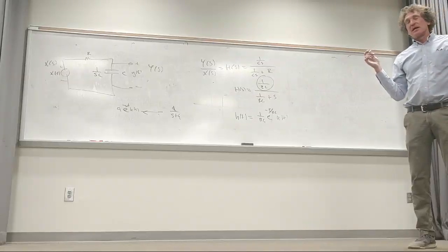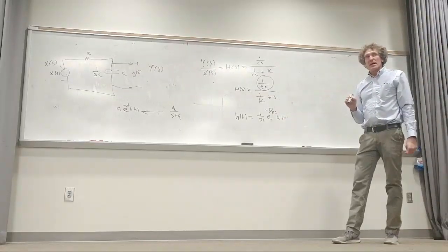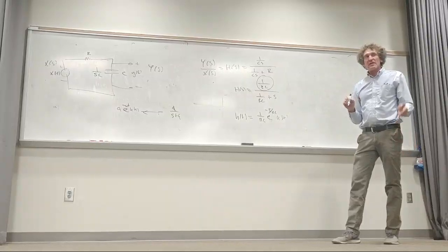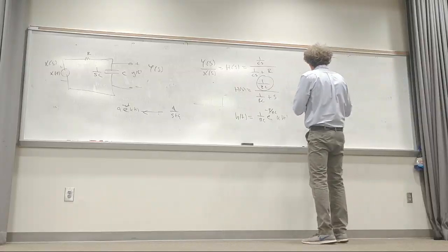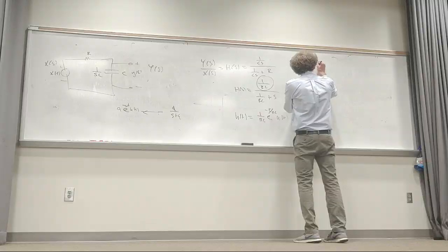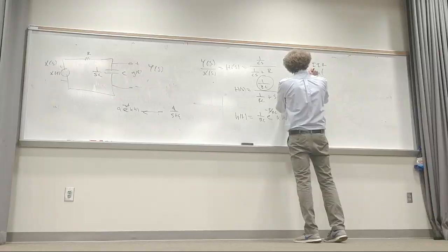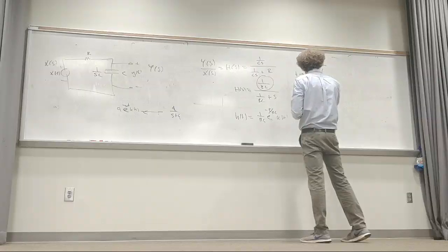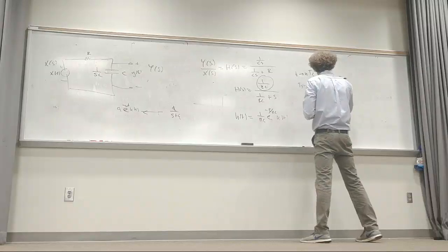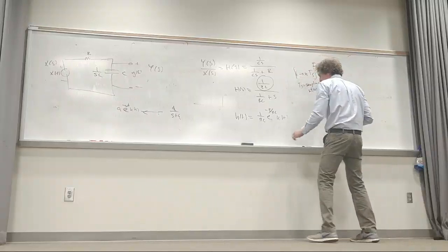All right, now listen. If you want to take this information first, this exists for all time, right? We could say the infinite impulse response, the IIR filter, impulse response of this filter, would be H of, and you let T become NTS, where TS is simply the sampling interval or time.